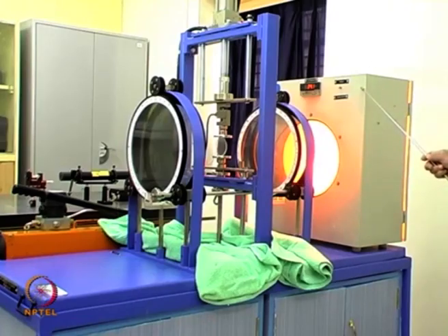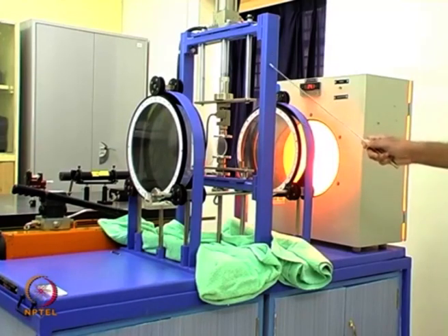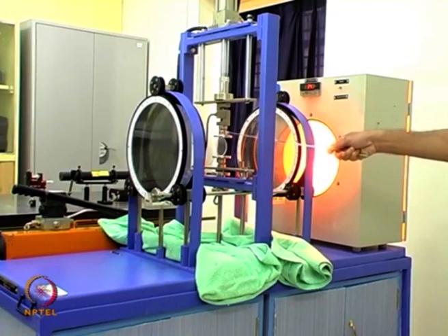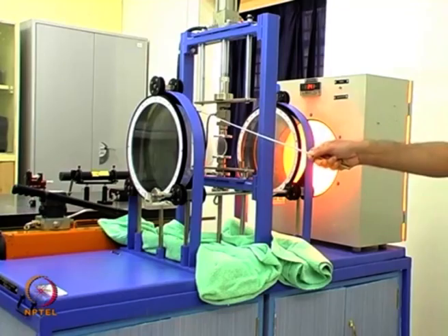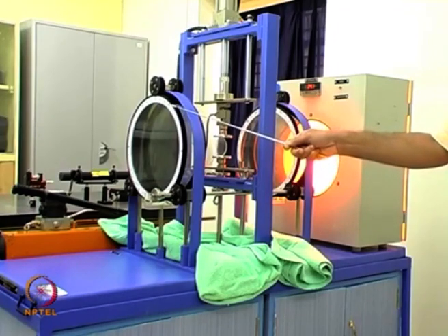This has a light source, and what you have is a monochromatic light impinging on the model. You have the first optical element, namely the polarizer. You have the second optical element, which is the first quarter wave plate. Then you have the loading frame. In the loading frame, you have the model loaded. Here you have a circular disc under diametral compression. Then after the model, you have the second quarter wave plate, and finally you have the analyzer.